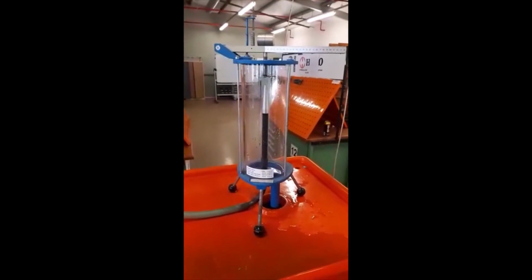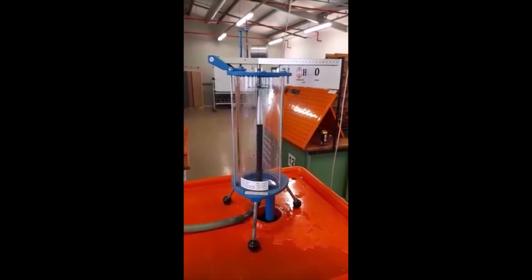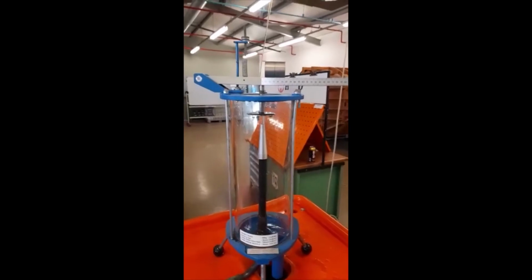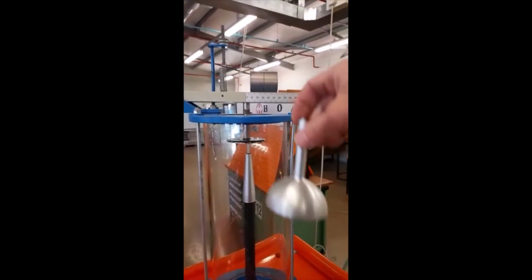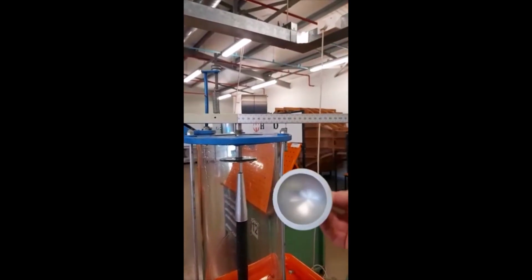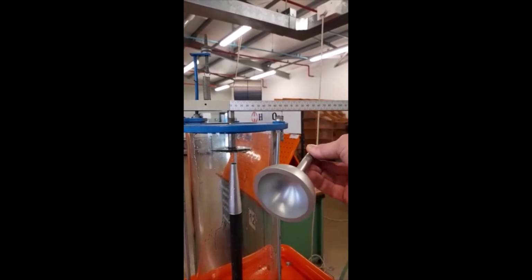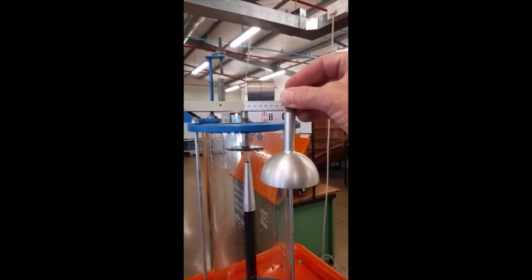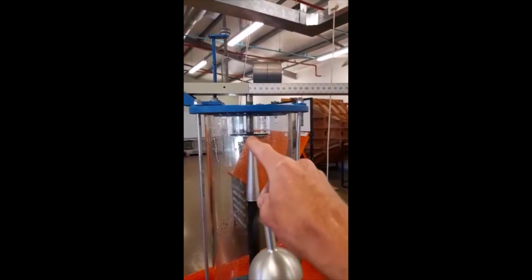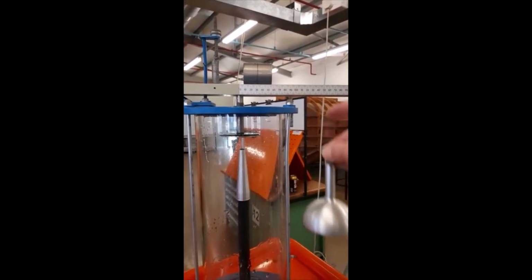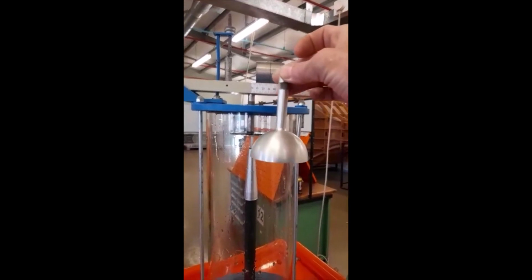And the next section, we're going to go through the method or the procedure on how to capture the data. We're going to do this experiment for a flat plate, which is currently installed, and then also on a hemispherical plate. And the method or procedure for the flat plate and hemispherical plate is exactly the same. The only difference between the two plates, the water deflection on a flat plate is 90 degrees, and on a hemispherical plate it will be 180 degrees.